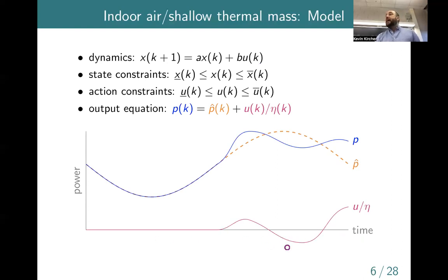So what that might look like if we plotted power versus time, you can think of this as being like maybe a day. And I guess this could be a hot day where we're doing air conditioning, say. And maybe this is the night period where the demand is low. And then this is the afternoon here where it's hottest outside and the demand is highest. So our baseline power might be this kind of P hat thing. And then we perturb, by taking some action, we heat more or less than we normally would have. So we do this kind of perturbation thing. And if we add the two of those, we get the actual measured power that we're putting into the building.